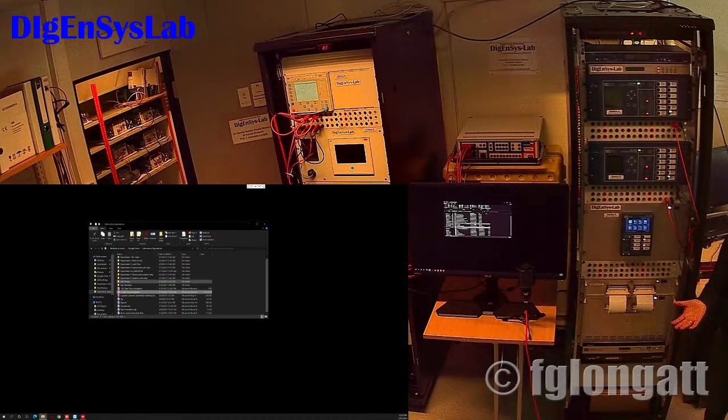You must be familiar with the word bits of the relay, because every relay has different word bits. It depends on the model. It doesn't matter if it is the same brand. Let me explain the phrase word bit. A word bit is a very specific language that the relay uses internally to decide its functionality and whether the relay trips.